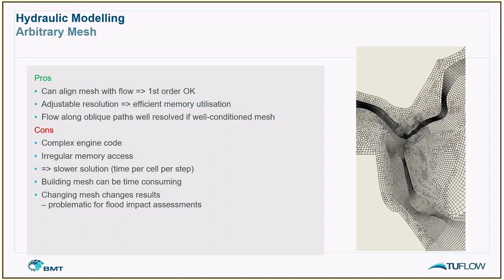Also, with meshes, it's not always possible to obtain mesh independency. Quite often there is a need to show the benefit of a particular flood alleviation scheme or an option relative to a baseline model. Modelling the option scheme involves different model geometries which will affect the local mesh, as you'd probably expect. But occasionally they can lead to subtly different meshes, or mesh configurations in more remote locations.